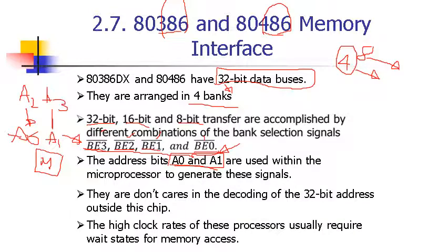Good. Of course, this makes a higher rate of operation of data transfer of your microprocessor. So you can increase the speed of your processor by either increasing the clock, making your processor operate at a higher clock frequency, or you widen your data bus. Make your data bus carry more bits in a clock cycle.